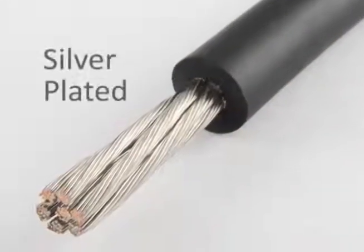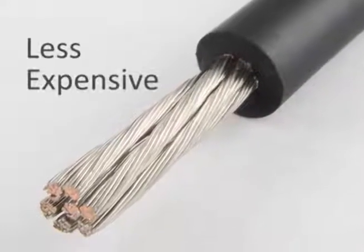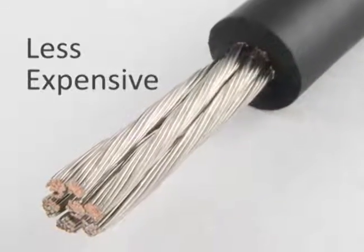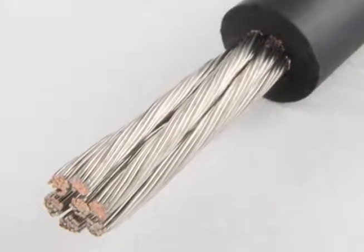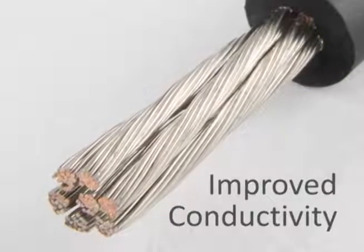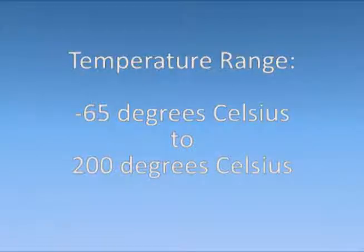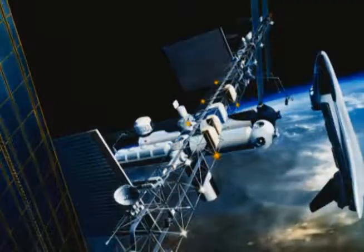Silver is the most conductive material, but its high price limits its use to very select applications. Silver-plated wire is a much more common option. It's less expensive than using silver alone, and it still provides many of the excellent conductive qualities of silver. It not only improves the wire's conductivity, but it also allows the wire to operate over a wide temperature range, from -65 degrees Celsius to 200 degrees Celsius. Silver-plated wire is commonly used in aerospace applications.